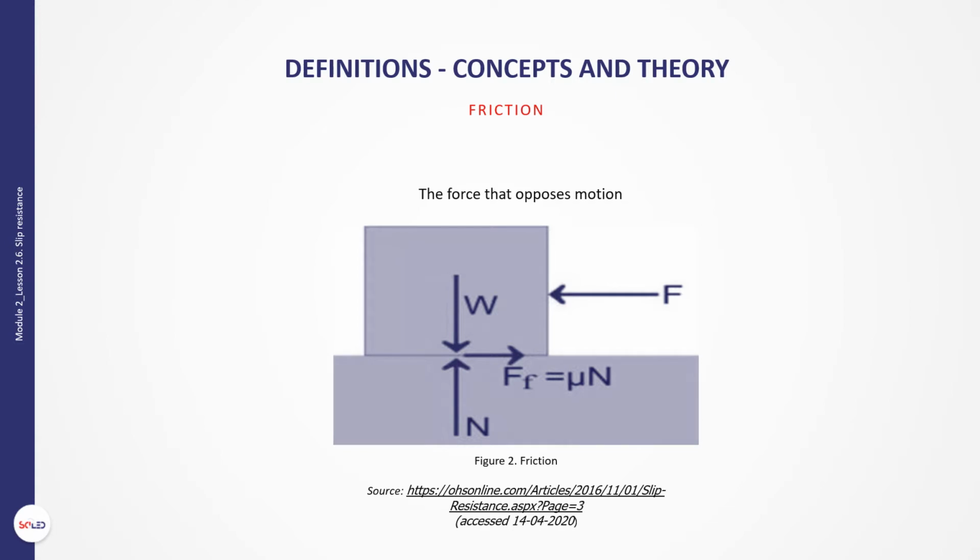The coefficient of friction, COF, is commonly referred to as available friction. Often, the term available friction is used interchangeably with slip resistance. For example, assessing the slip resistance of a shoe sole means determining the amount of available friction it provides or its COF. A larger COF represents a larger friction force and a greater resistance to motion. Conversely, a lower COF represents a smaller friction force and a lower resistance to motion.